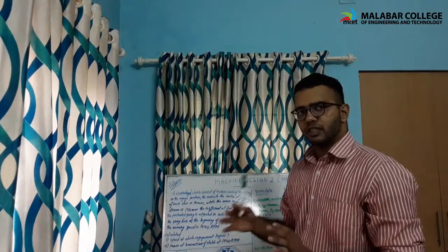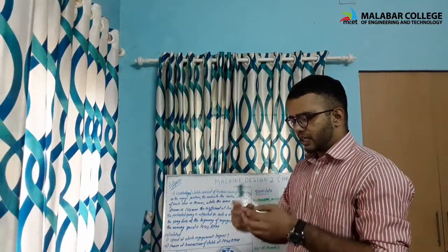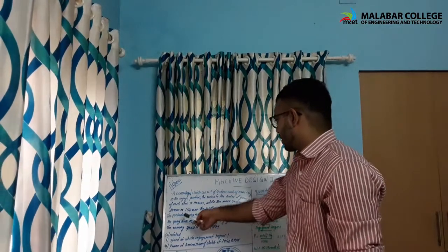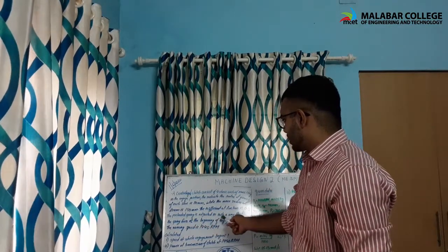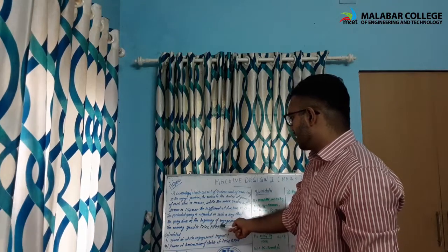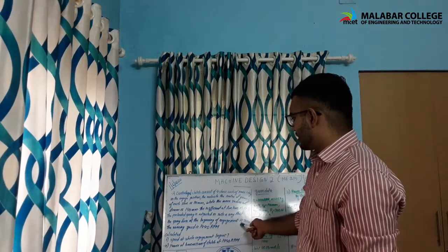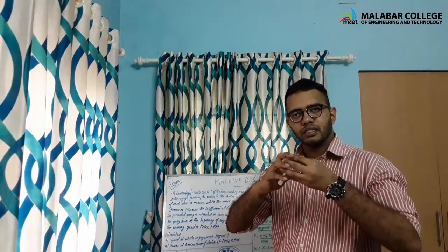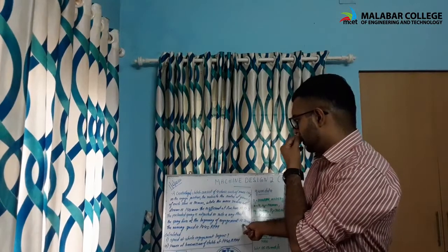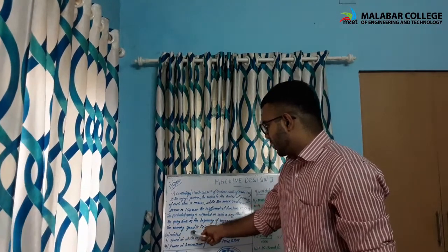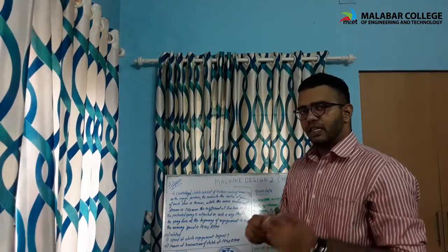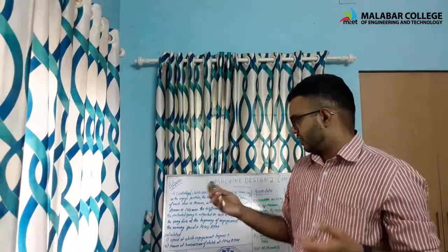Always, for any mechanical device, when it comes in contact there will be friction, and it's 0.3. The preloaded spring is adjusted in such a way that the spring force at the beginning of the engagement is 700 Newton. The running speed is 1440 rpm.